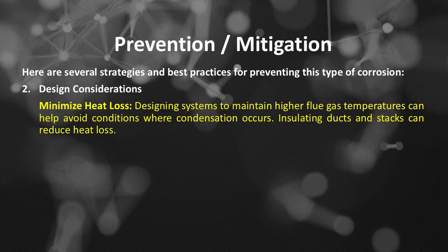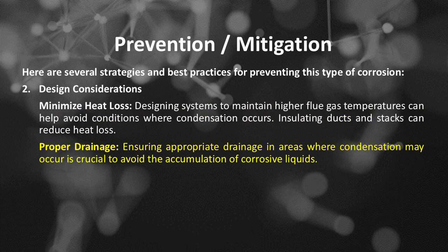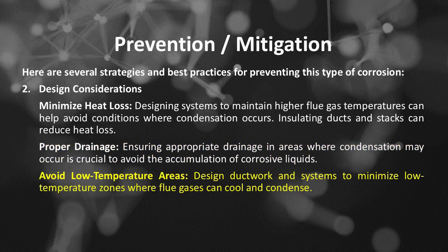Minimize heat loss. Designing systems to maintain higher flue gas temperatures can help avoid conditions where condensation occurs. Insulating ducts and stacks can reduce heat loss. Proper drainage. Ensuring appropriate drainage in areas where condensation may occur is crucial to avoid the accumulation of corrosive liquids. Avoid low-temperature areas. Design ductwork and systems to minimize low-temperature zones where flue gases can cool and condense.